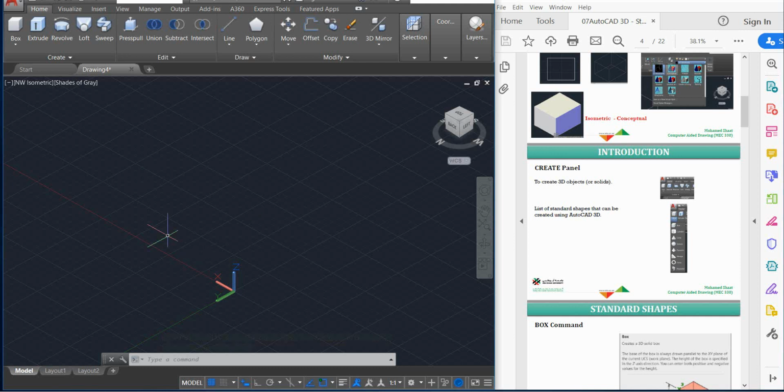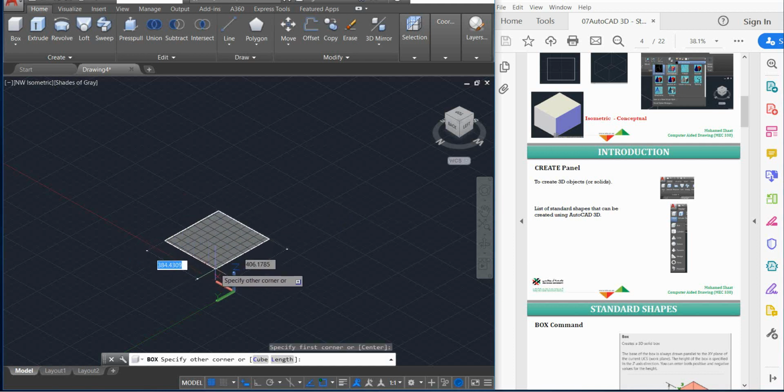Can we work over 3-dimensional working sheet? Yes, we can build it automatically. Like if we choose box, and it's gonna be much more recommended if you would like to build an object, especially in the start. So you're gonna see how you're already extending the object. Like for example, AutoCAD asks us to specify the first corner. So this is the first corner, then it's gonna ask me to specify the other corner. Now I can see the base, how it builds. So this is the second corner.